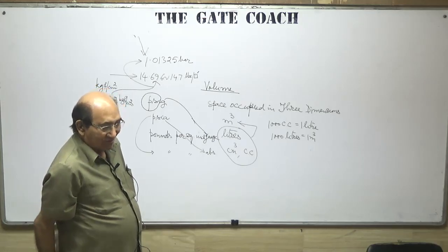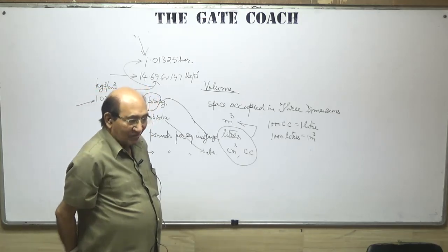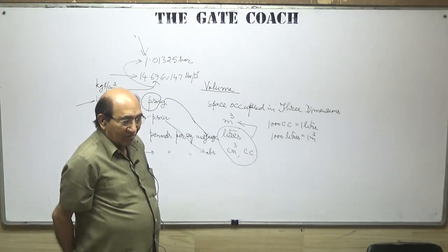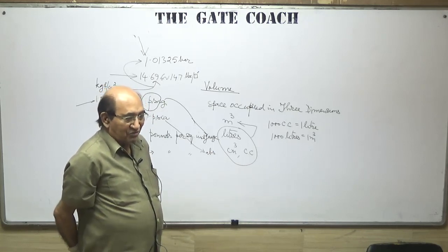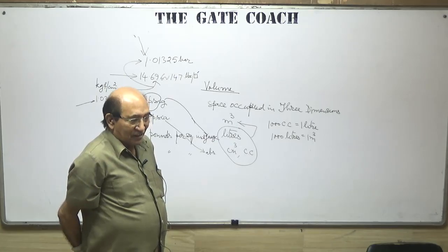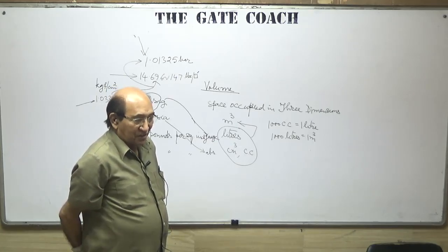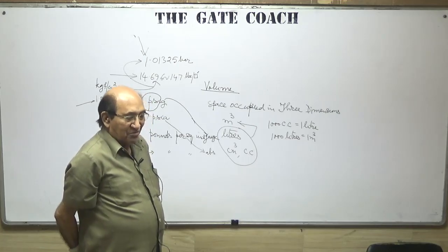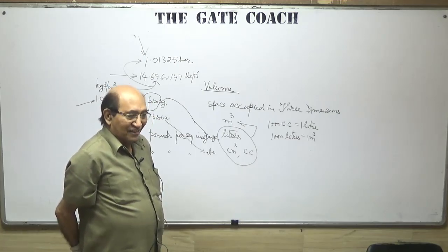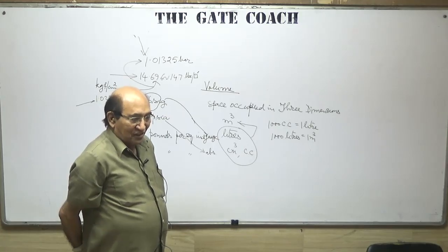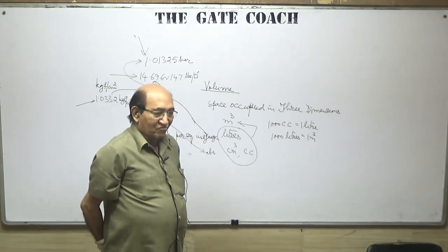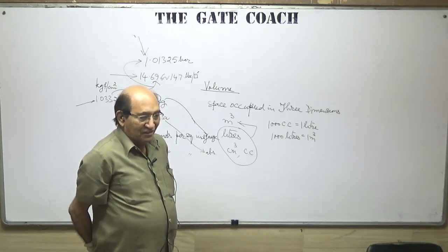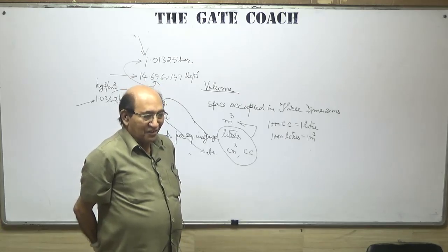Yes, sir. And second question is, do all the devices measure the gauge pressure only, or can we also measure the absolute pressure directly? No, because instruments, all which we are using, they are the gauges. They are reading the pressure of the system. And pressure of the system read with the help of any gauge is called gauge pressure. No instrument shall read the absolute pressure, as no instrument reads the temperature in Kelvin. All instruments are reading either in Fahrenheit or in centigrade.